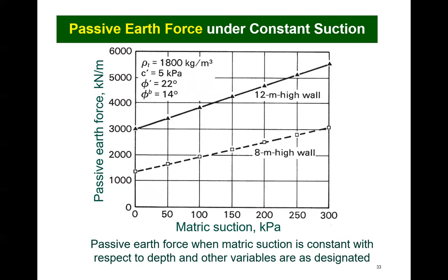In other words, historic earth pressure theories were calculated for a material with a cohesion intercept and a friction angle. Unsaturated soil behavior is assumed to simply be that of a soil with an increased cohesion, and that cohesion is quantified in accordance with the shear strength equation for an unsaturated soil.